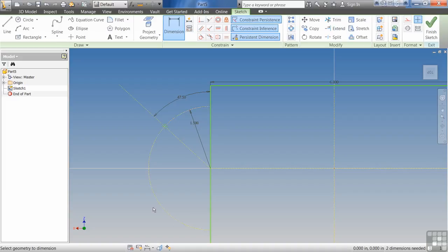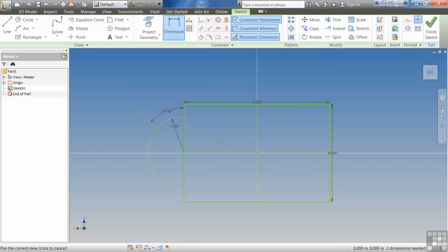I know that this part's going to have some kind of swinging gate, and I need to have a stop point for that gate. You know, that gate's going to be 2 inches long. It can swing out to, say I want to stop it at 45, or I want to stop it at 135, depending on which way it's going. I want to put a circle there. I'm going to put a dowel in there, and it's going to stop that swing. Then I can basically draw out that swinging path, draw out my gate, dimension it, where the 2 intersect, and that gives me my circle location. Don't have to do any geometry to figure out where that is. It's a very helpful tool to be able to do that.